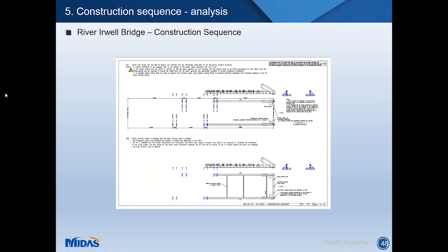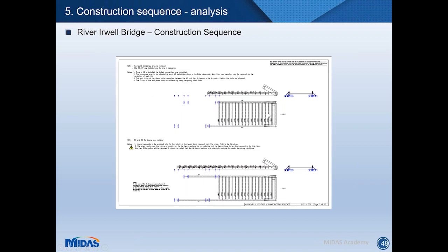The construction of this bridge starts from the construction of the tie beam at the north side. These are supported on asymmetric towers, as we discussed, and you can see the asymmetric towers here in elevation and in plan. And then it's time to put in temporary props and the first cross girder and the trimmer beam, and then we follow with all of the other cross girders here, and we erect the central tie beam, and then we continue in a very similar manner.